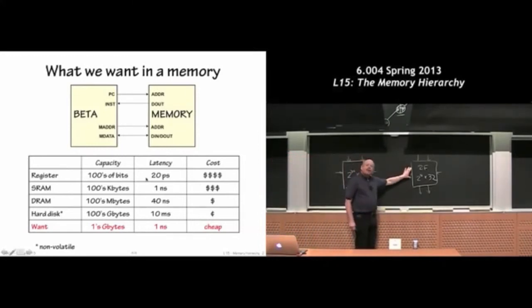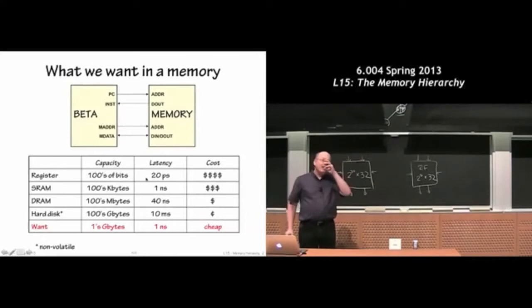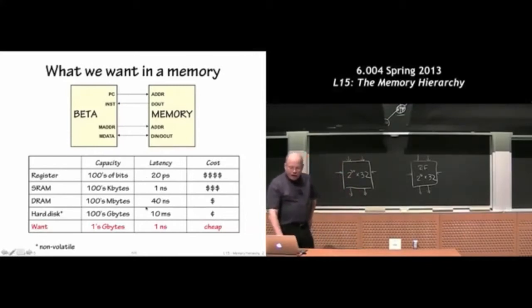They're very expensive to build. That speed is because we're devoting a fair amount of silicon area to getting that. And the fact that they're small also allows them to be fast, because the capacitances involved in the signaling wires are small because they don't have to go very far. At the other end of the spectrum, we go through both static RAMs and DRAMs. I'll say a little bit about the technologies of those in the next couple slides.